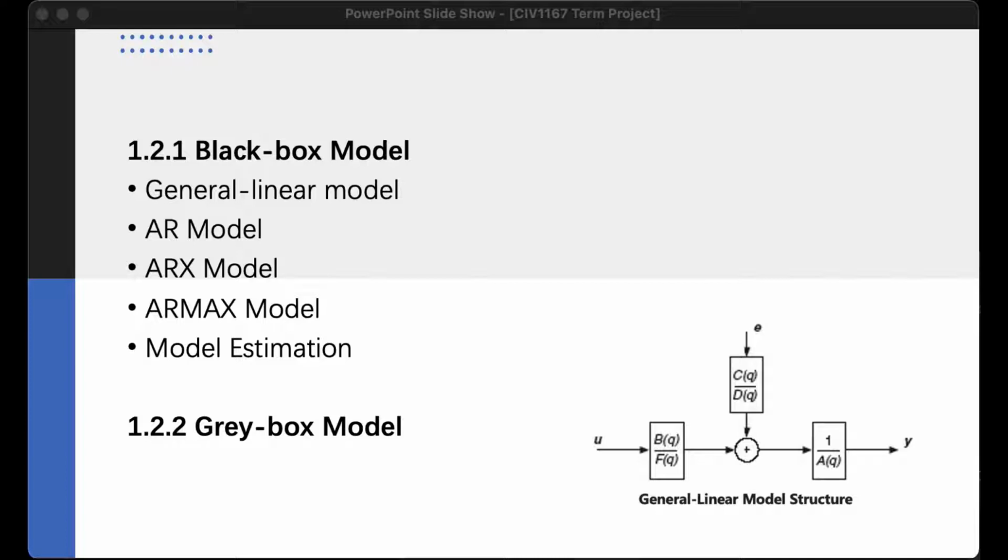Then, compared with polynomial models, the state space model is similar to a first principle model. The identification procedure does not involve nonlinear optimization, so the estimation reaches a solution regardless of the initial guess. Moreover, the parameter settings for the state space model are simpler than polynomial models.